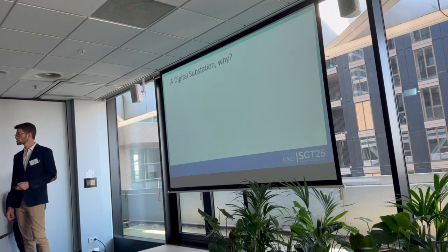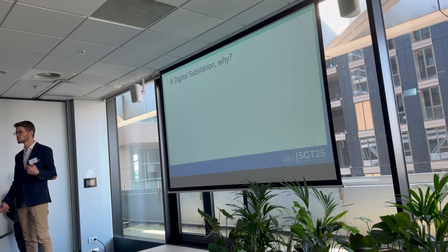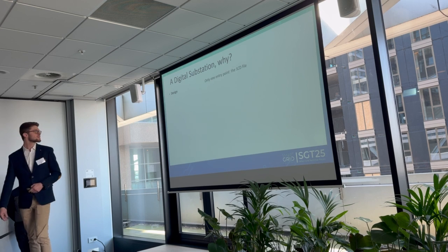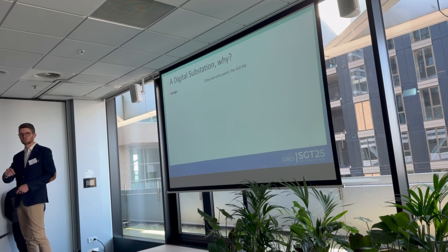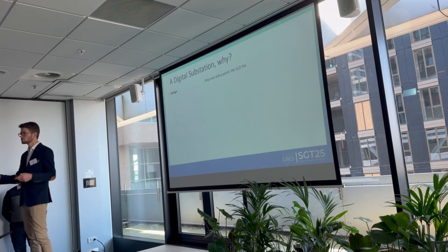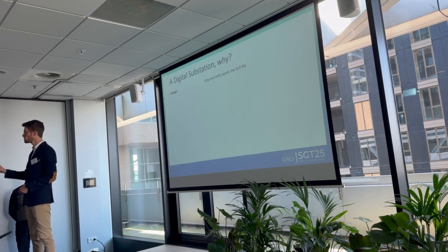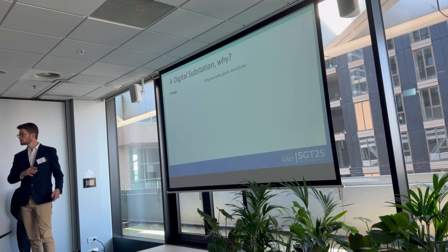So, a digital substation. The question is why? We will not do it for fun, because we saw there are a lot of challenges, so why did we choose to go this way? Mainly about the design. We spoke about the design. What if there could be a design made by one file, the system configuration description, only one entry point, you configure everything, the logic, the 850, the logical nodes, the communication, everything configured in one file, you deploy it and then it works.